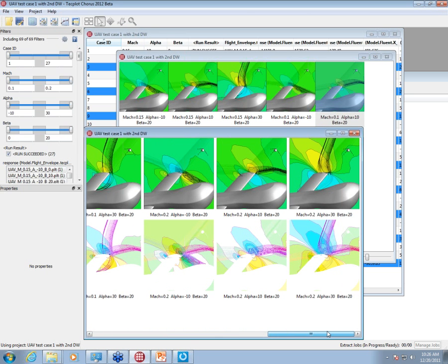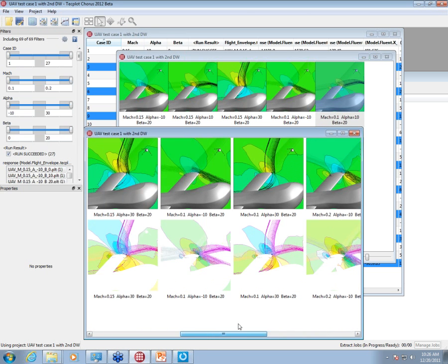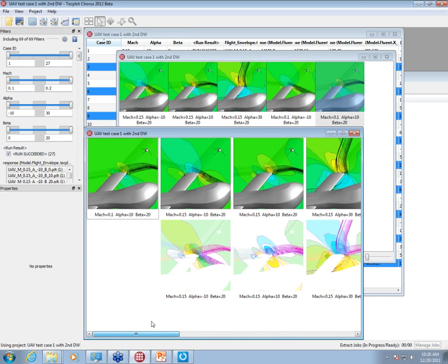The advantage of the pixel difference is that it's very fast. And the second advantage is that it's insensitive to variations in the geometry. It'll show up, but it's a robust difference. Even if the geometry changes substantially, you can do that difference. Which is, again, convenient if you're doing grid sensitivity analysis and you're more of an exploratory CFD practitioner, then you can use this image difference very quickly, even though you can't do a point-by-point difference.